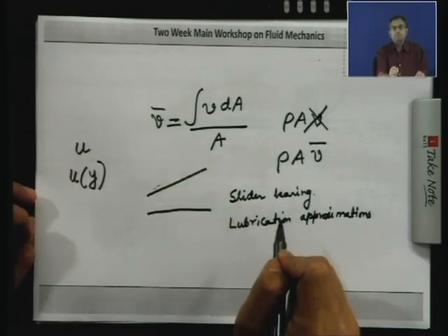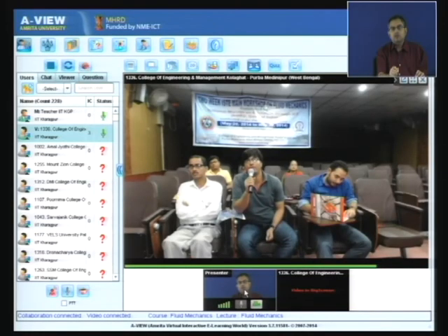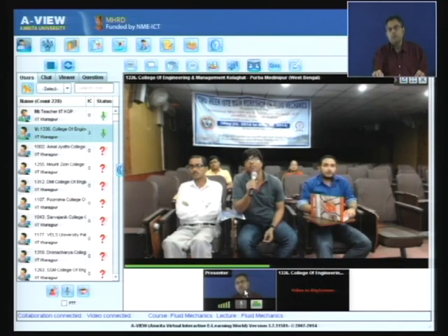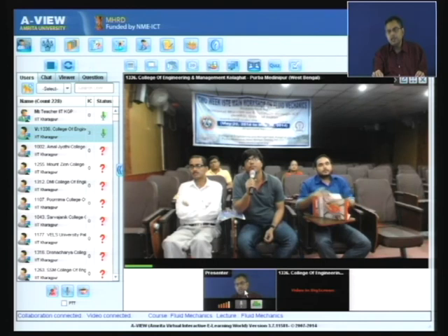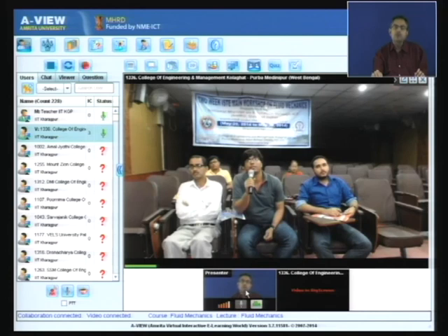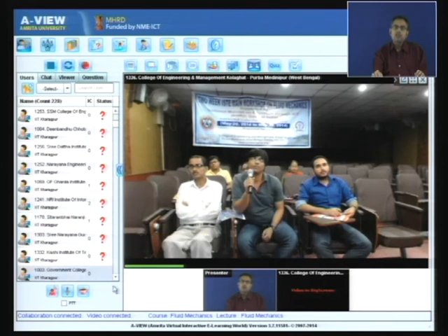Can we visualize it? Suppose a flow is there, can we know whether it will be unidirectional flow? You can get the velocity profile by many methods. You can inject a dye, or you can put tracer particles in the flow and illuminate the flow field by a laser light and visualize the flow. That is commonly done in particle image velocimetry, or PIV. So it is possible to get a visual description of the velocity profile, and from that you can conclude whether it is unidirectional or not.